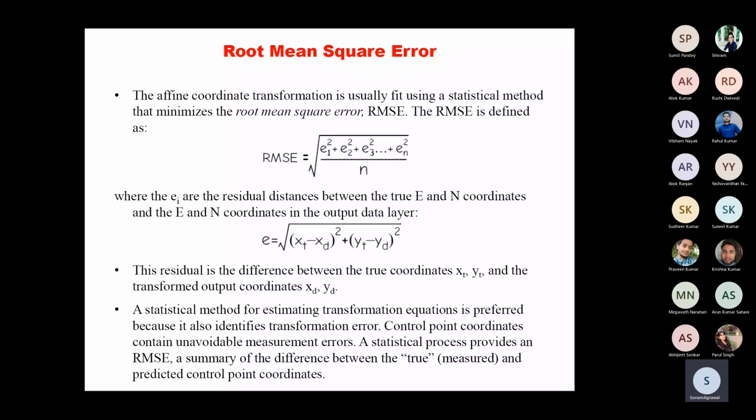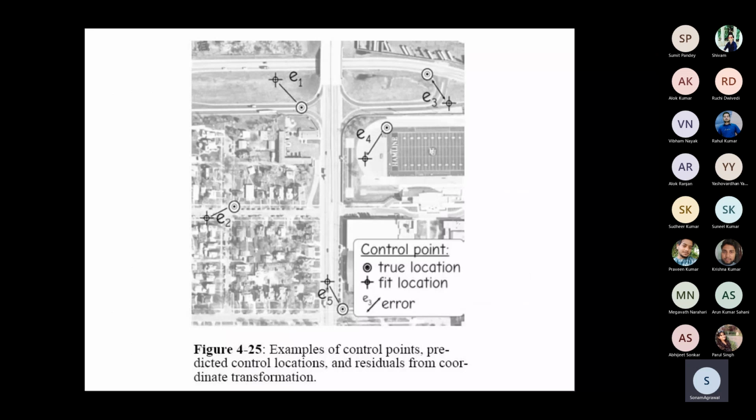Once the affine transformation is done, for every pixel, for every cell of the raster data, the latitude, longitude or northing and easting value is computed. So basically there will be an interpolation of all the points. Thereafter, there is a process of resampling. Why do we perform resampling?